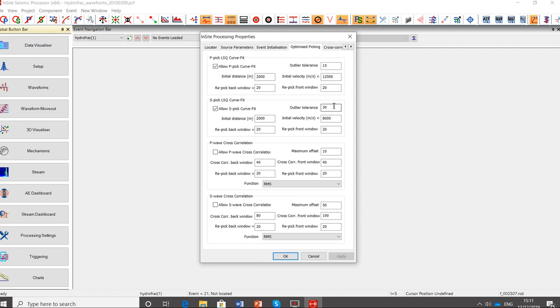It will run a first auto picking as we've done now, and then it will refine this picking by using the first detected arrivals for all of our array, fitting a curve that will fit well all our detected arrivals, and adjusting the outliers in our picking around the curve that has been fitted to the best arrivals.